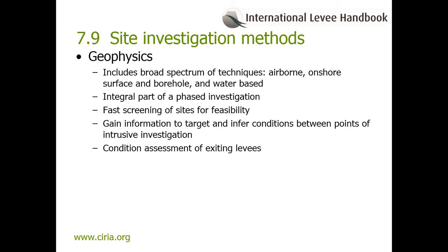Where geophysics is used within a phased investigation, it can most beneficially be done during the early phases before the detailed intrusive investigation, where it can provide a fast site screening tool during feasibility and help target intrusive investigations to maximize the information obtained and to infer ground conditions between points of intrusive investigation. It can also be used to aid in the condition assessment of existing levees.